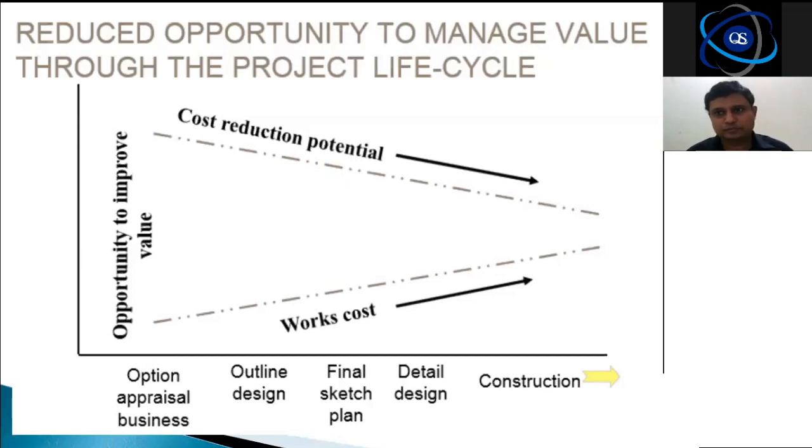Suppose that instead of conventional block work, a smart structural engineer comes up with an option. We will use autoclave aerated blocks. I hope you have heard about autoclave aerated blocks. Autoclave aerated blocks are lighter in weight and have better thermal performance. Yet it is a little bit costly if you are transporting from a different area.